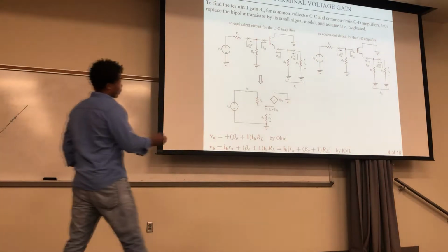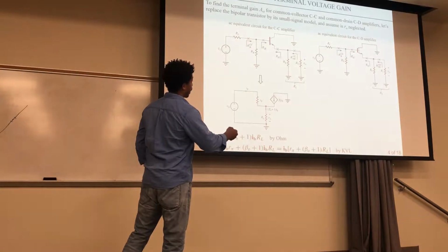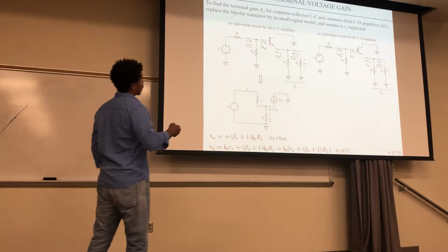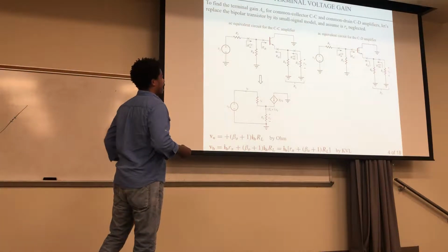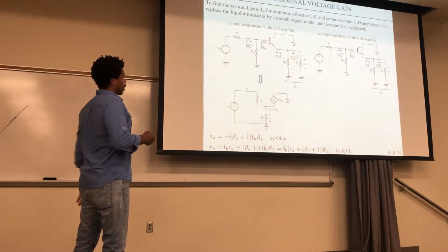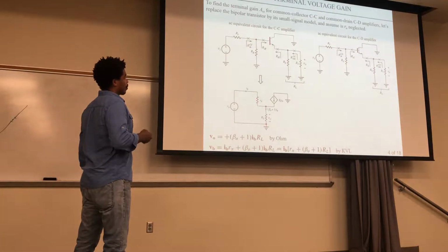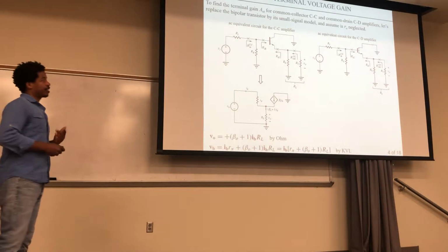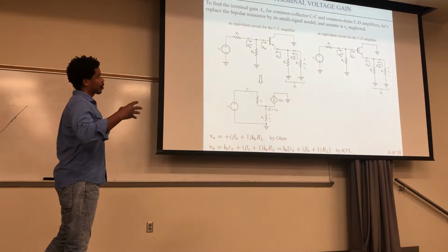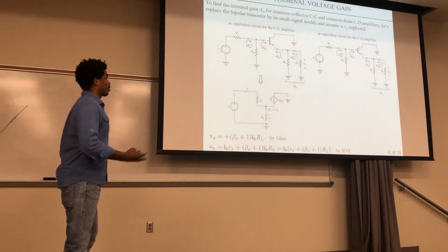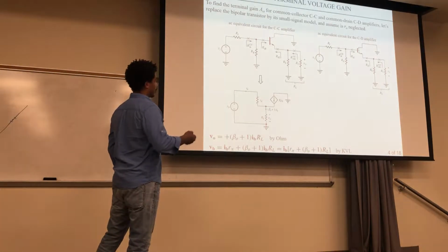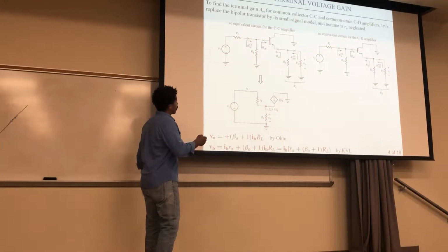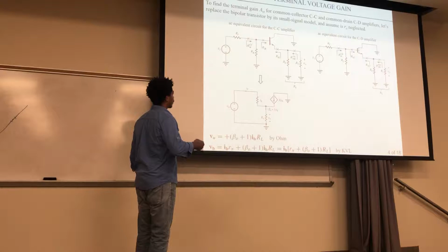Okay, and also, this over here is the FET part. So this is the BJT, here's the FET, or this is the CC, the common collector, here's the common drain. And there's like a nice relationship between the two. Whatever you do to this, you can easily convert your equation to this by just assuming your R pi and your beta 0, your current gain, get very large, like they just go to infinity, and then that's the equation you get from over there. So in this case, we're going to convert this to this right here.